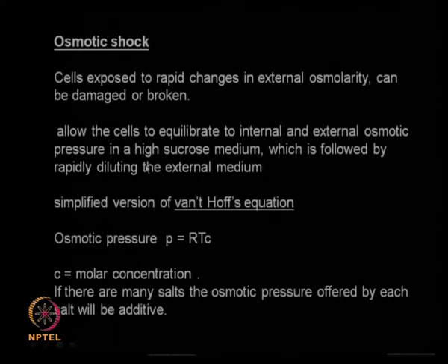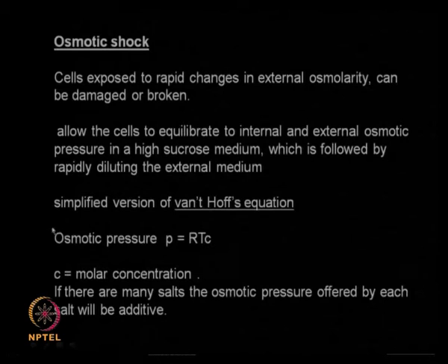So this pressure depends upon the concentration of the salt that is present, and if you look at the Van 't Hoff's equation, you would have all studied it in your thermodynamics, maybe in second year BTech or first year MSc. The equation says that the osmotic pressure is equal to, in a simplified version, R into T into C. R is your universal gas constant, T is your temperature, and C is your molar concentration of the solute present.